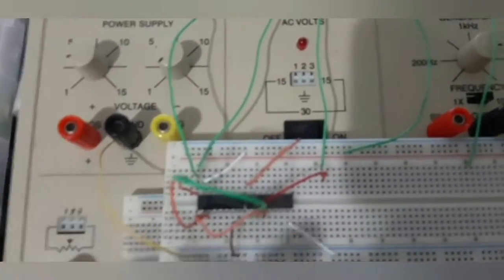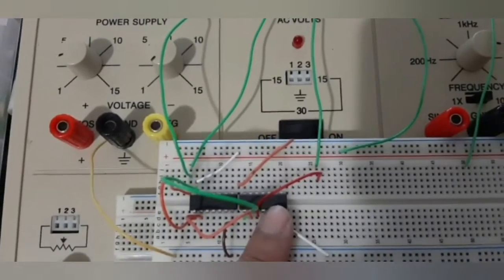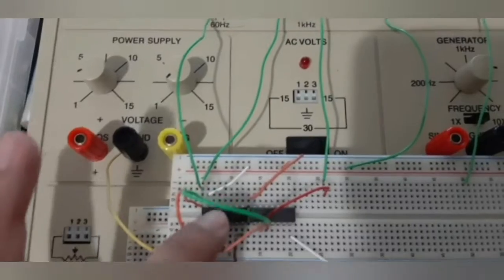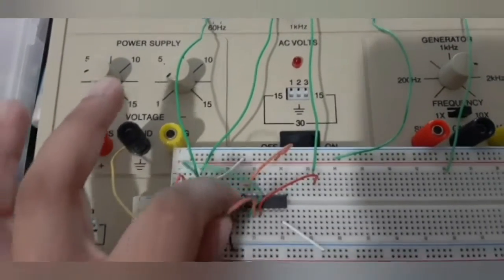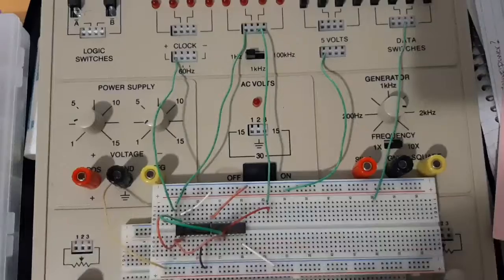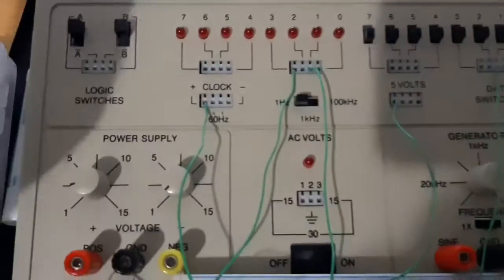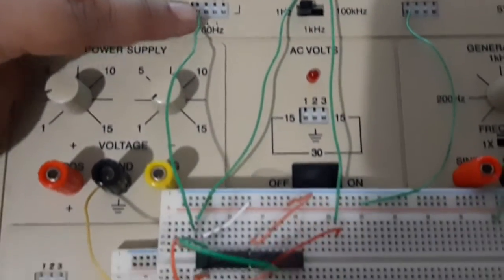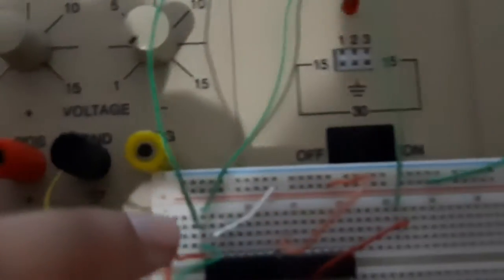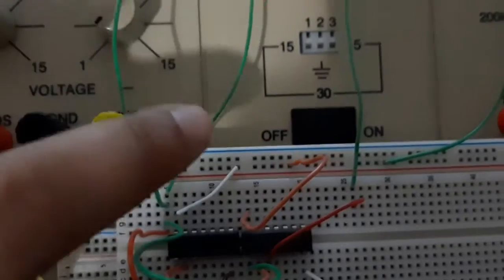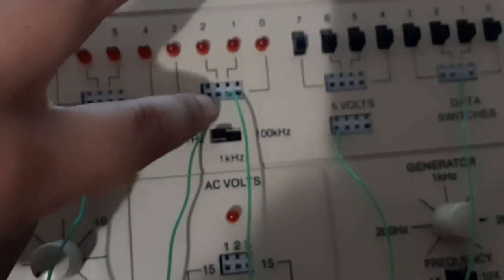One thing I didn't mention, the chip I was using earlier was 74LS08. That is the AND gate chip. And the inverter chip I have right here on the left is 74LS04. So going through this circuit, we have the 1 Hz square signal in this row. I'm going to focus in, which has one wire going to LED number 3.